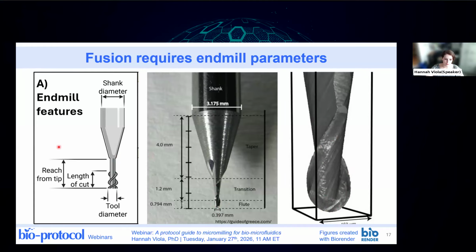And these are important features because to make our cutting simulation, we have to tell the machine exactly what this tool looks like so that it can properly simulate the tool path. We need to know how fat the top of the tool is, how long it is till the actual part we work with so that we can avoid collisions and make sure that we are not drilling too deep and then colliding the part with this taper part.